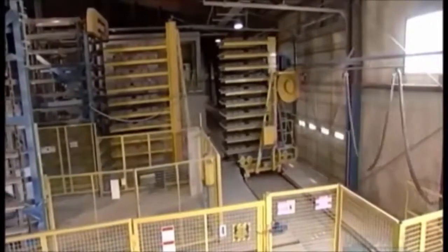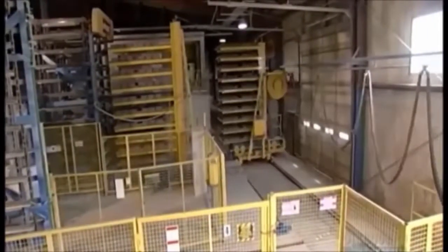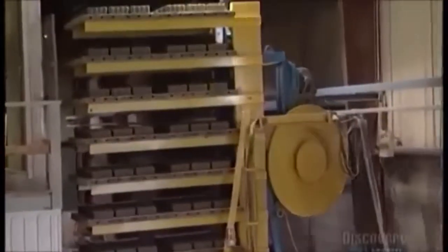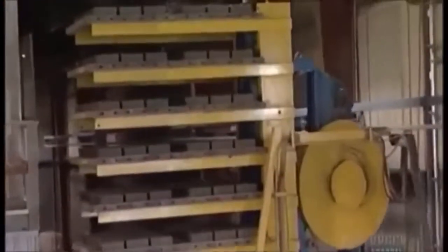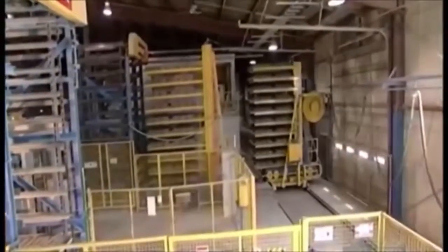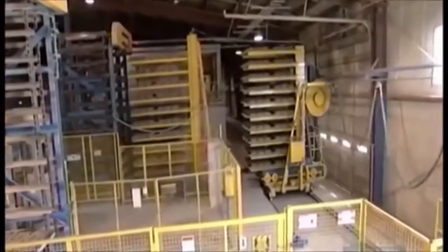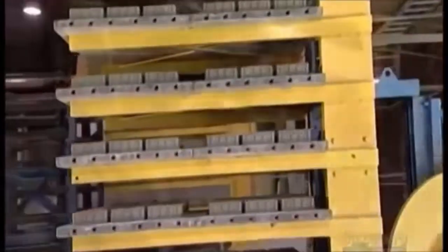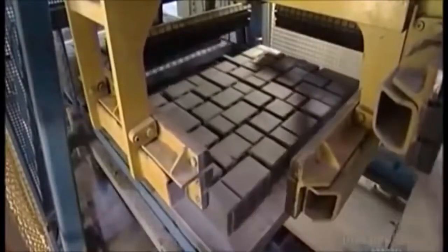The pavers actually generate the heat due to a chemical reaction from the combination of cement and water. About 12 hours later, the finger wagon carts the pavers out of the kiln. They're now 70% cured as a result of the chemical process that binds the cement, sand, and gravel, causing the pavers to harden. The rest of the curing will happen over the next 28 days.